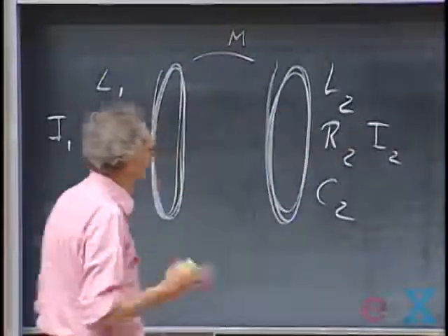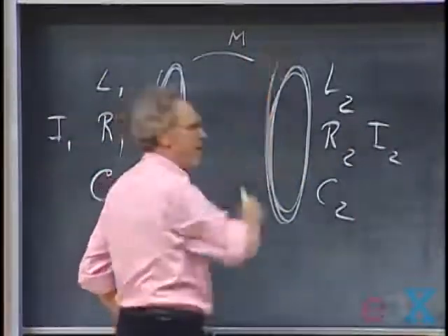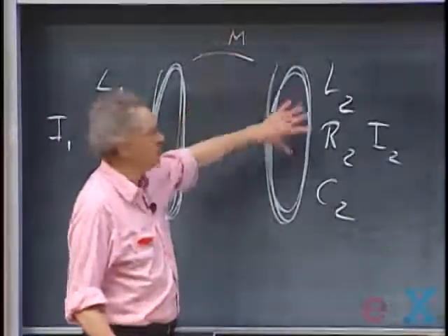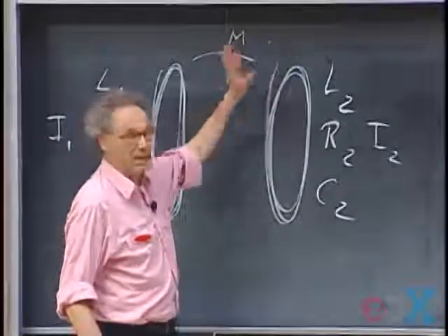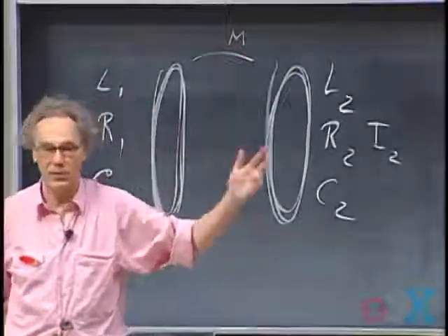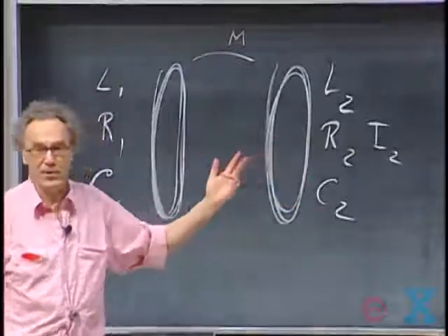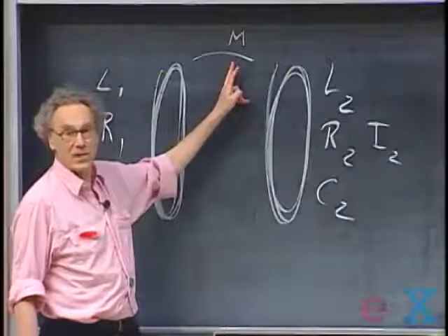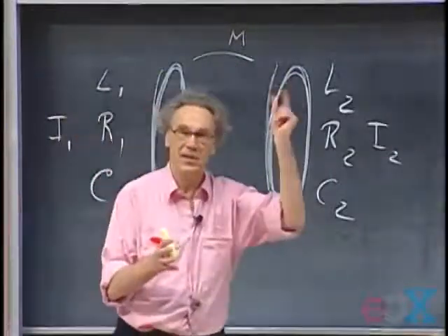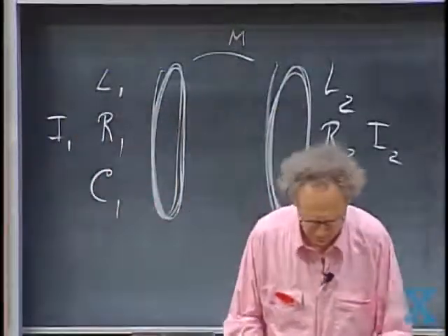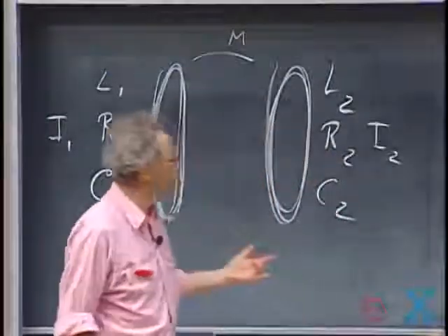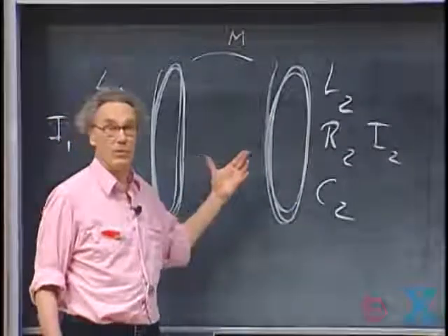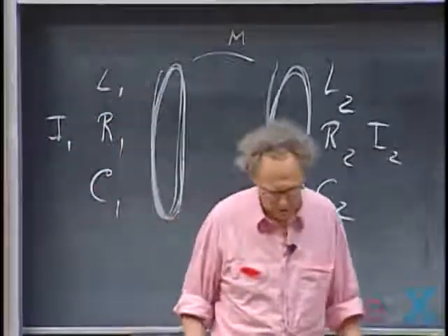And now someone brings in metal. You bring in a chunk of metal, and the metal will experience the magnetic field flux changes. It's AC, of course, always. In the metal, it will start building up eddy currents. And so the eddy currents will change the magnetic coupling between these two loops. And so M changes. And when M changes, you go off resonance, and bingo, your alarm goes off. Clearly, and very unfortunately, this never works for plastic bombs. You must have conducting material that you bring in, so it must be a metal.